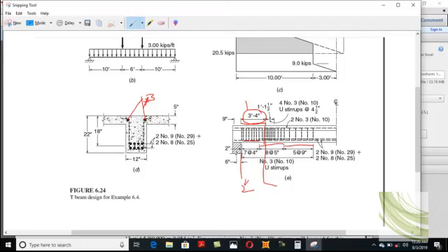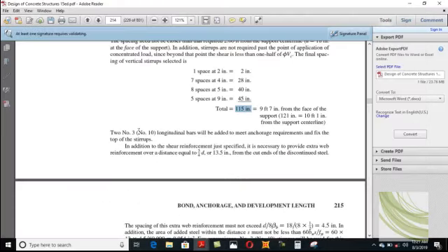Okay, because they act like a confinement bar. So stirrups are suspended from these 2 bars. So they are provided only for suspension purpose. Number 3 bars, 2 in number. This basically means anchorage requirements and fixing the top stirrups at their own place.